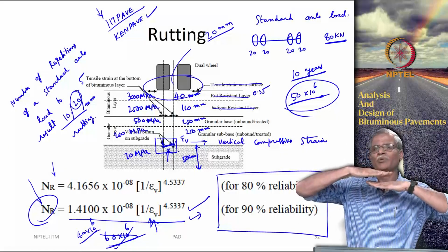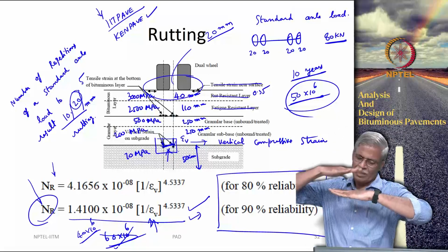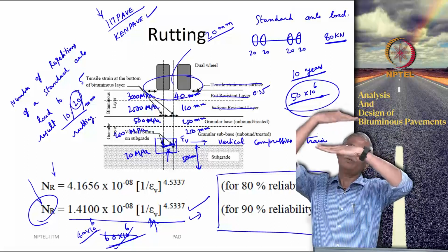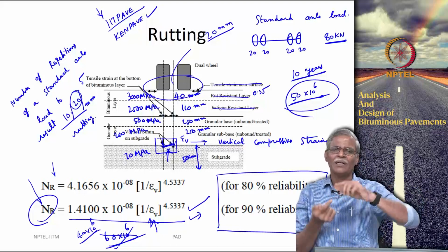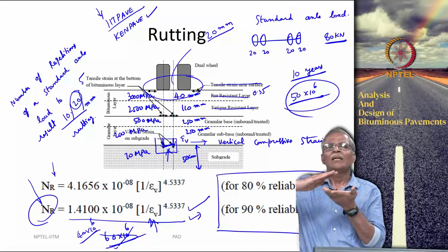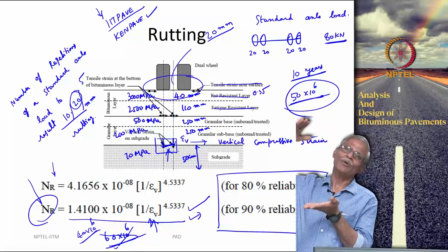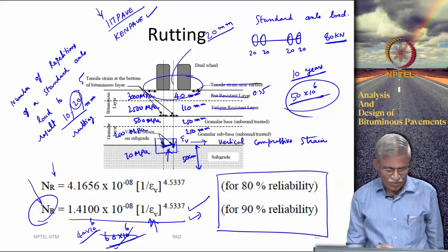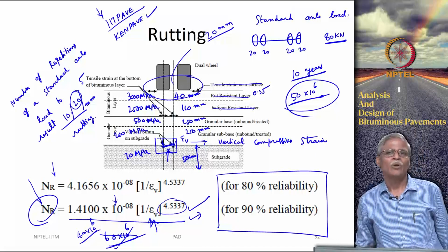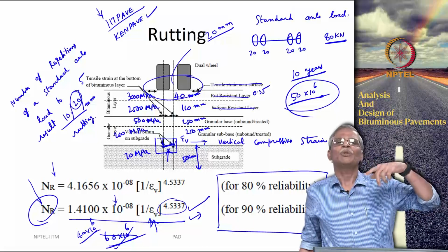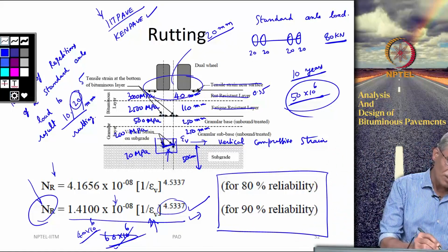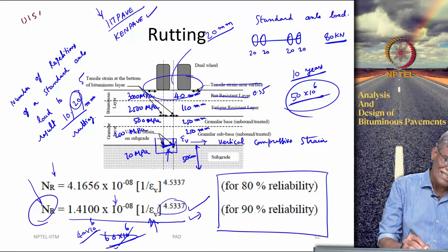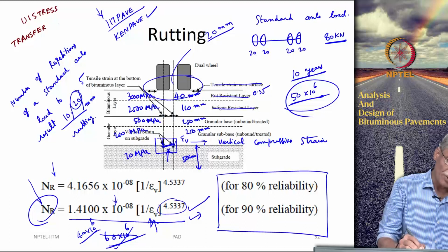So, what we are assuming in bituminous pavement engineering is, we basically assume that each and every layer is stacked on top of it like this, and which is the weakest layer? The lowermost layer. If the lowermost layer, if you could limit the strain, it is assumed that all the other layers on top of it can handle things, and this is where some of these empirical factors, especially these factors, play a critical role. So, you measure the strain at one place, but you translate it into rut depth at another place, and that is why these equations are called distress transfer functions.